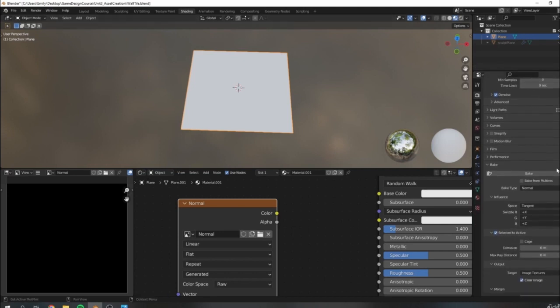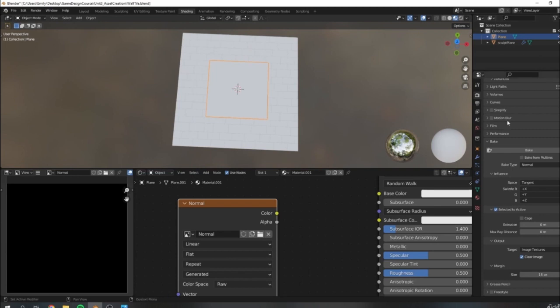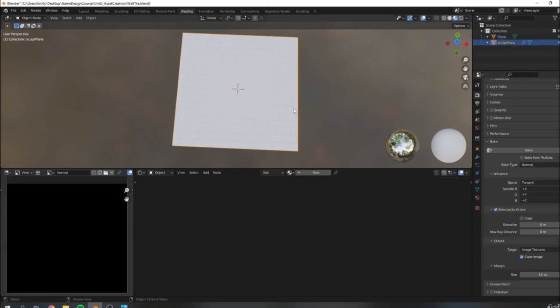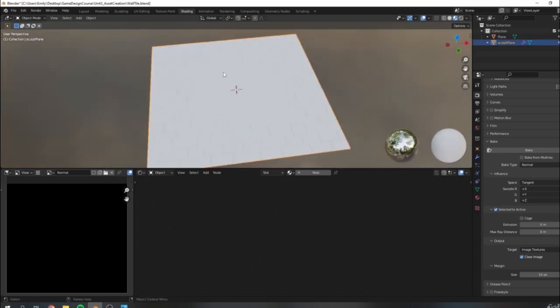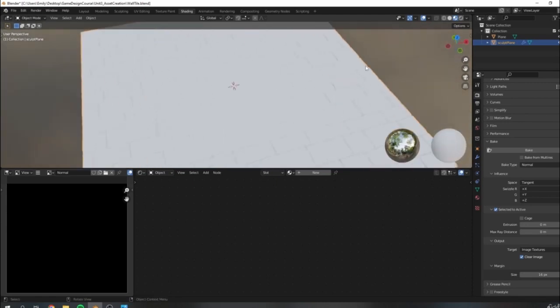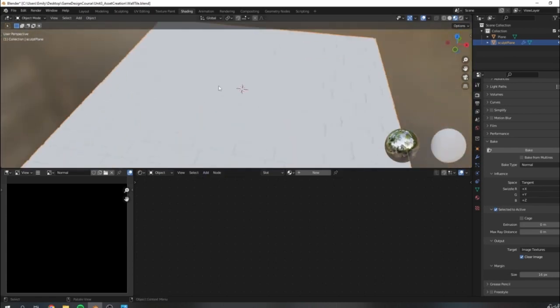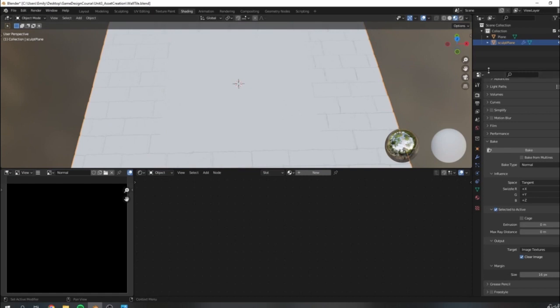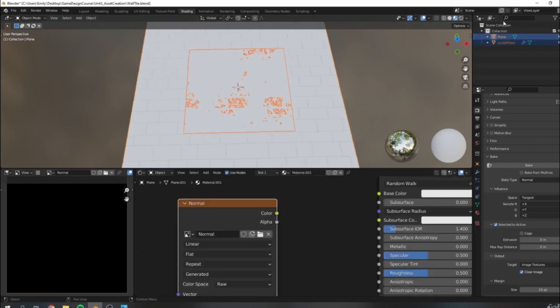When you have multiple objects in the scene, you need to specify to Blender what you are trying to bake. So we're going to select our sculpted plane, our high res, 8-meter plane, and then shift select our new plane, so that we still have this plane selected and it will turn a dark orange, but our active object will be whatever we selected last. Because these are right on top of each other, Blender is having a hard time selecting them. So an alternative way to do a multi-select here is to select first our sculpted plane in our outliner and then hold Control and select our image plane here.